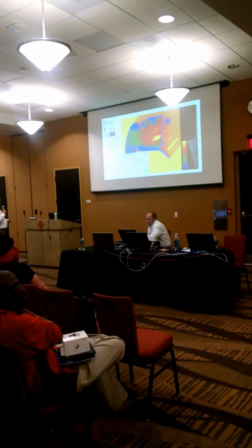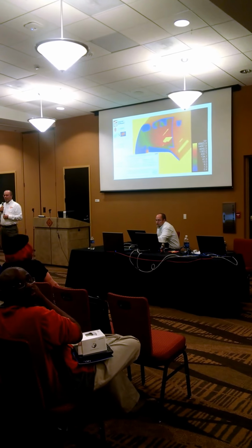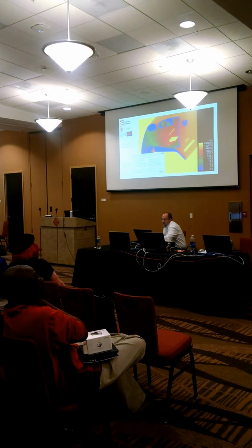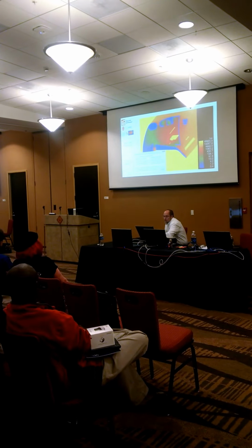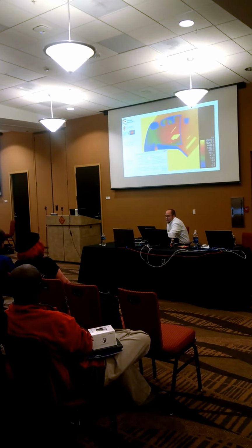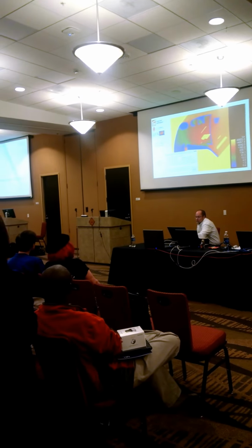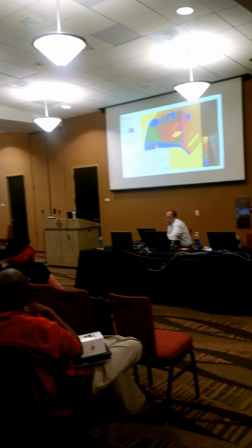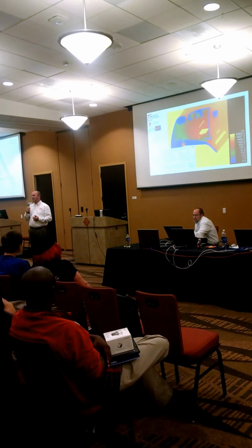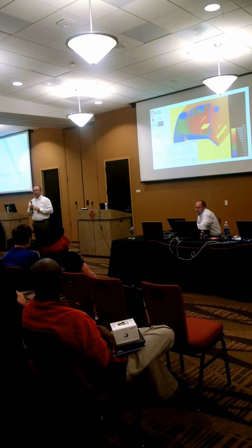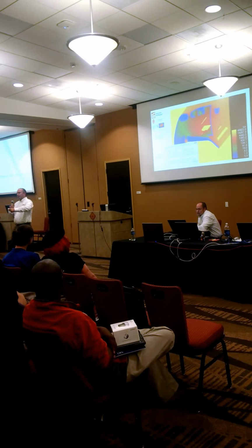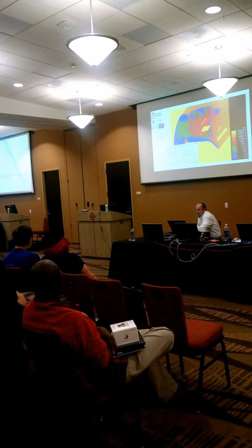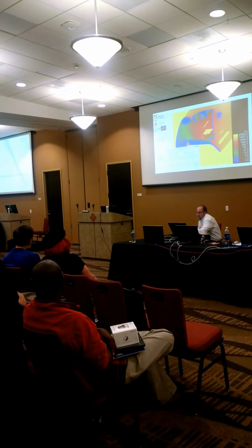We also took out another extension tool via the web, using the Revit model, which is this actual lighting analysis for Revit. It's reading the model, doing some analysis based off LEED, and giving you a pass-fail. It's very much like a COMcheck if you've ever done that in the past. We had to manually sit there and enter that stuff, teach it your walls and this and that. This is automatically reading that information from the model and doing the processing for us.